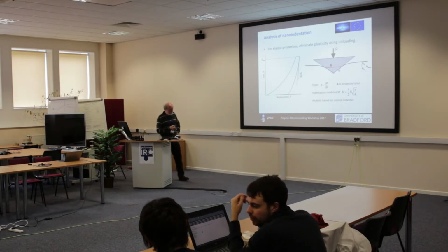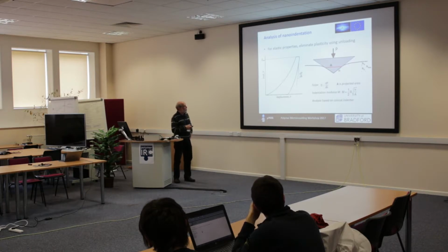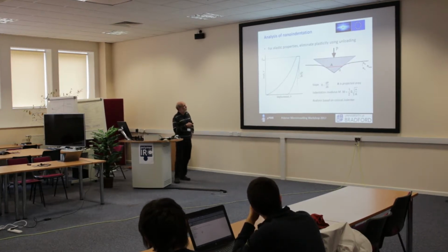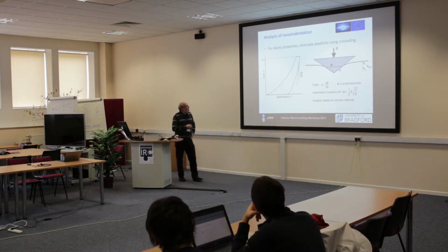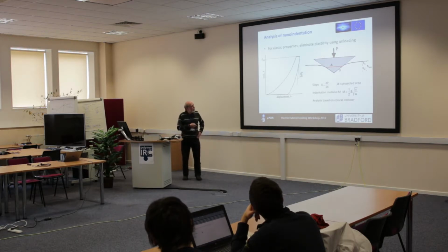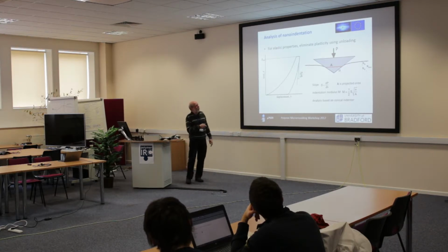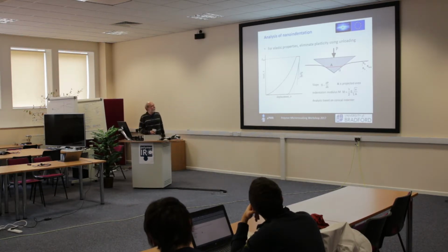So you measure the load and you know the displacement of your indenter as you push it into the surface. So as you increase the load, you're increasing the plastic zone. You're putting more and more yielding into the system. So as it goes down, you yield more material. Okay, so on the loading, you've got plasticity contributing to the force here.